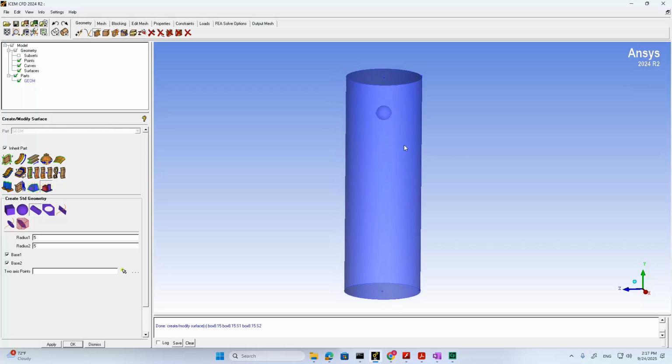Then you will have a unique solution. So here I'm going to first make sure that I can apply boundary conditions to those boundaries. I will apply those boundary conditions to those boundaries in Fluent. Right now I'm using ICEM, the meshing tool. So here I will do some preparation work to facilitate the application of boundary conditions in Fluent, which is I